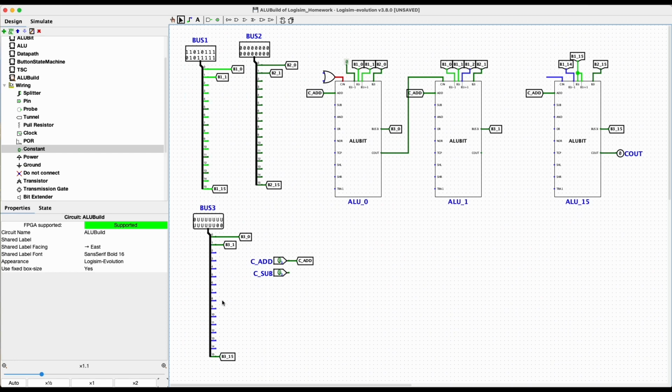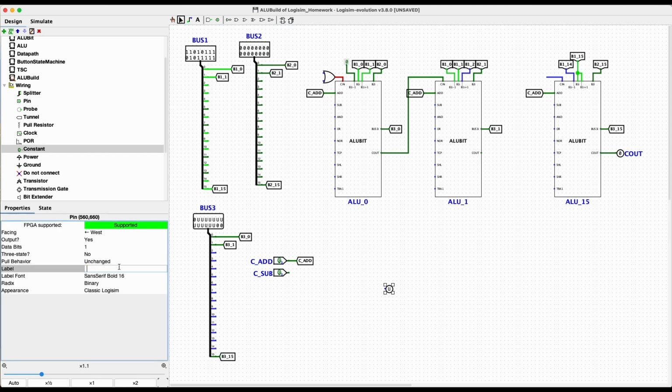We don't want to branch when it's equal to 0, only when it's greater than 0. So we can't just look at the sign bit of what's coming out of our ALU. We have to look at every single bit and make sure they're all low. So there is going to be one more output, and the output's name is going to be called 0, and it will be high when all of the bits are low.